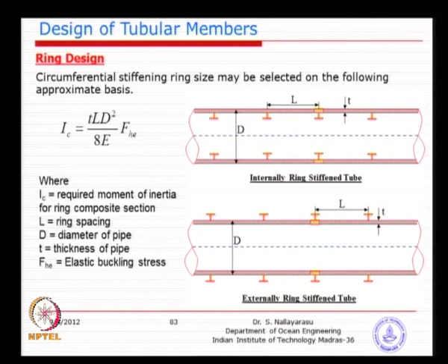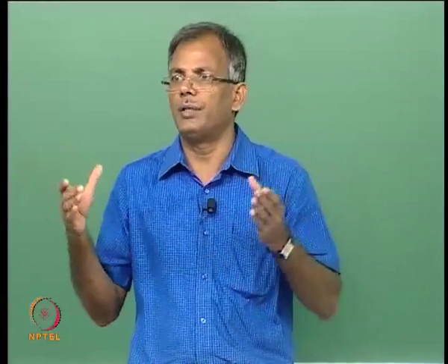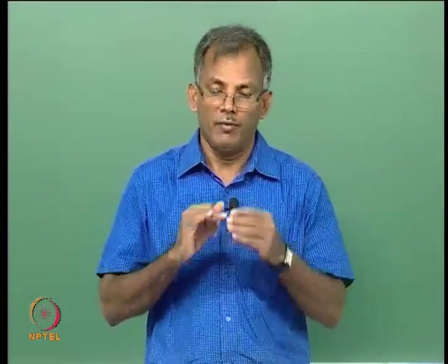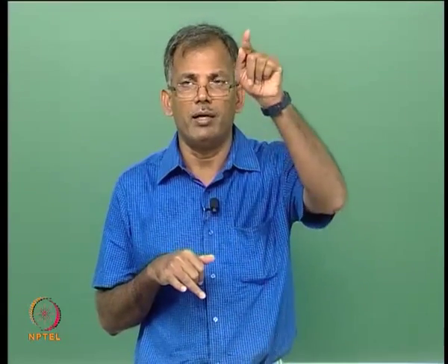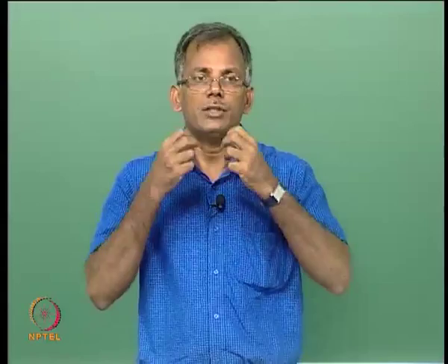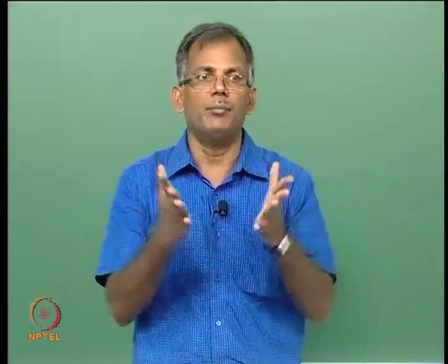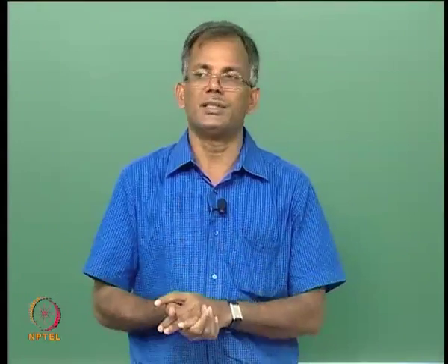You know why the local collapsing happens? Basically, local collapsing happens not just primarily due to hydrostatic pressure, but also due to fabrication imperfections. At any one location you may have a small imperfection which can onset buckling. Once that forms, then you will see that the next section starts to buckle.